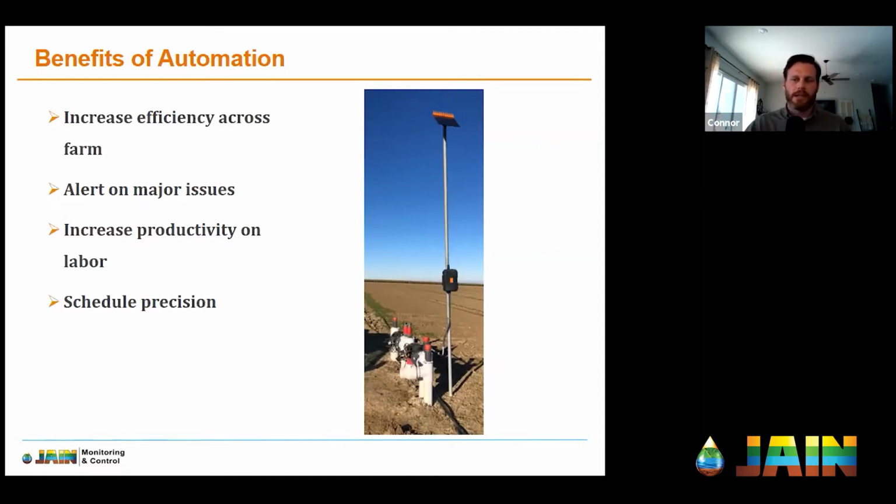So that's exactly what's pictured here. We have a C3 connected to a couple of valves. And so this grower is now not only able to turn the pump on and off, but while the pump's running, he can then rotate his various irrigation sets in the surrounding fields. So in a sense, we actually are increasing our overall efficiency by being very precise with our schedule application.